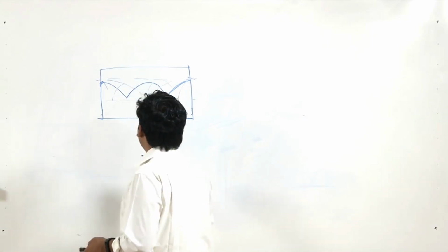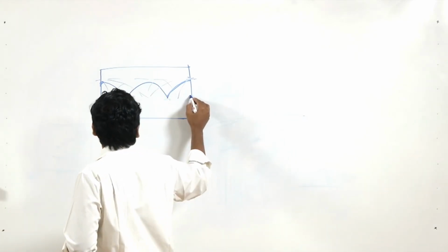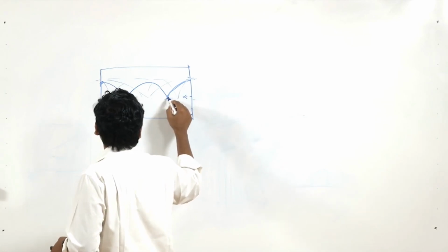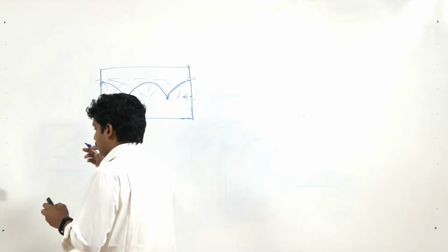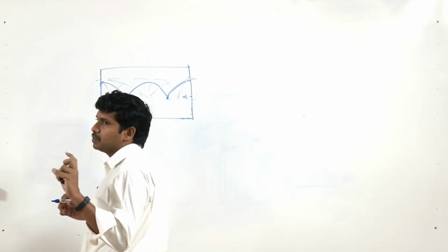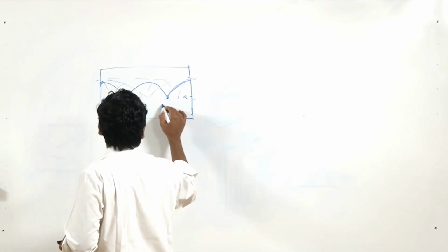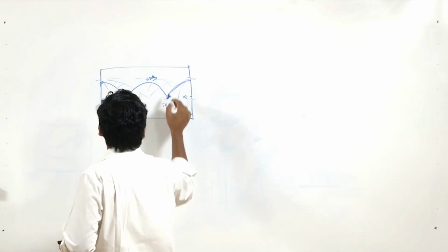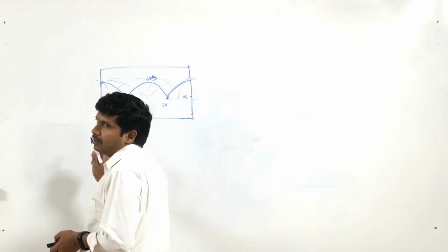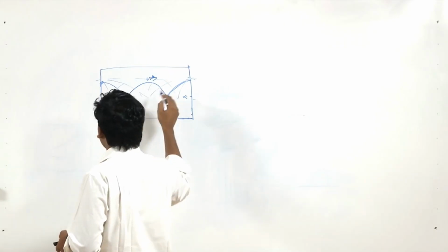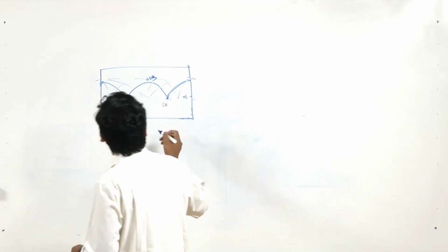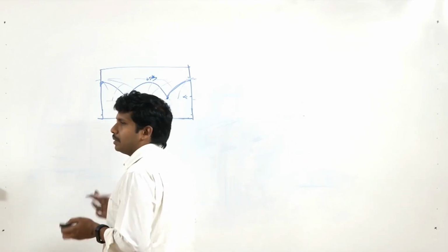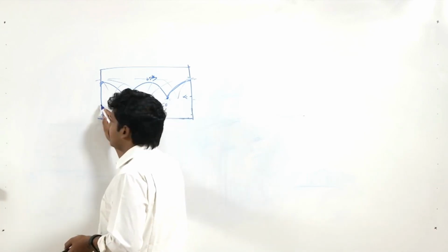What happens is, if you are a receiver and you walk along from this end to this end, you will find a minimum sound. Say the noise level from the source is 60 dB, at this point you may be experiencing 50, here it will again peak to 60 or 65 dB. So as you walk through, you will find an 8 to 10 dB difference. I may be exaggerating the numbers, but you will find a starkly perceivable difference as you walk from one side to the other.